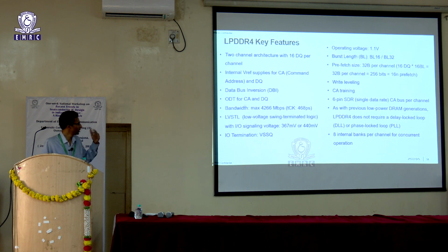And SDR stands for single data rate. We have a 6 pin command address scheme, and we do not need a DLL for LPDDR because the system is very small. The overall footprint is going to be much smaller compared to your DIMM module. This goes into your mobile, so you do not have much room to keep the SOC and the memory far apart. It is more or less packed one over the other or right next to each other. So the interconnect delay between your SOC and memory is very limited here, and you can afford not to have a DLL or a PLL.